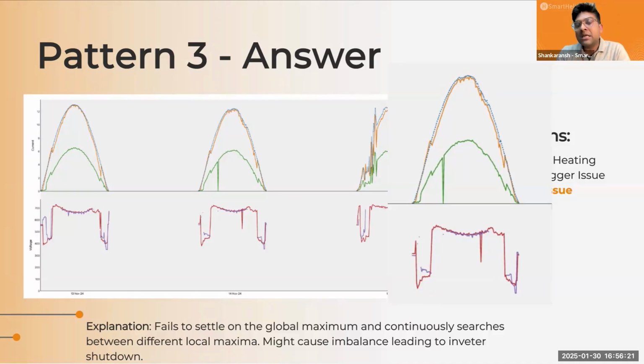In a PV plant, there cannot be just one fault. There are multiple faults. So the trick here is to be able to separate all the other issues that might lead to a response from MPPT that will alter the current and voltage, and then only observe the behavior of the MPPT in isolation. So that's what gets a little complex here.